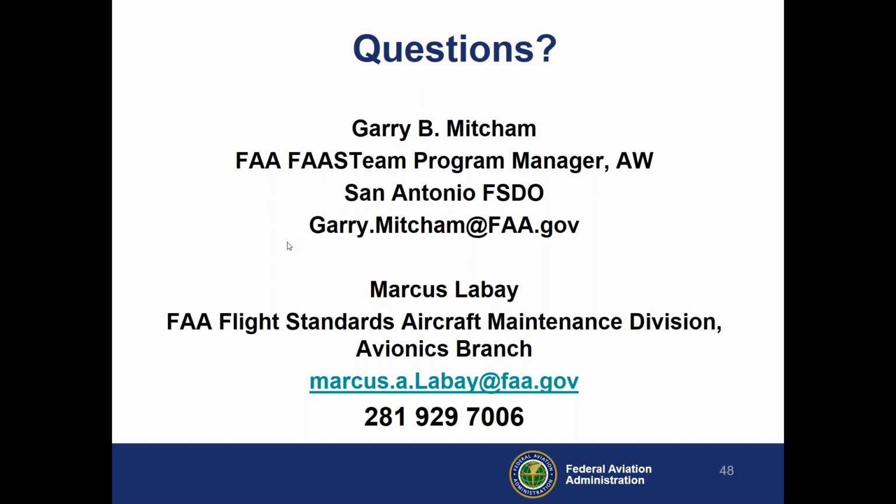If you have an IFR 6000 or a TIC box, I believe they have a boot with them, so you can use the boot for one antenna and the coupler for the other. Again, the boot doesn't provide as much attenuation as a coupler does, but if you test it before you put your aircraft in the airborne condition up at any altitude, then you should be okay. And if not, you might have to purchase two of the attenuators, correct, Gary? That's an option, yes.